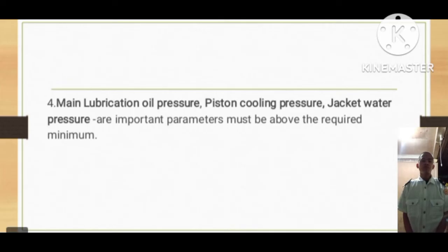Next, lubricating oil pressure. Lubrication plays a key role in the life expectancy of an engine. Without oil, an engine would succumb to overheating and seizing very quickly. Lubricant helps mitigate this problem, and if properly monitored and maintained, it can extend the life of the engine. Lubrication in an internal combustion engine begins in the sump, commonly referred to as the oil pan. From here, the oil is pulled through a strainer by the oil pump, removing large particles. The oil then goes through the oil filter. It is important to note that not all filters perform the same.